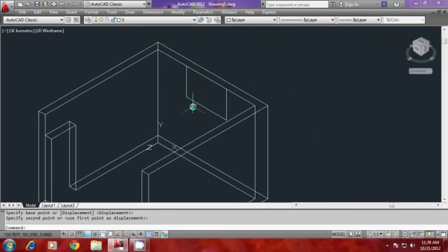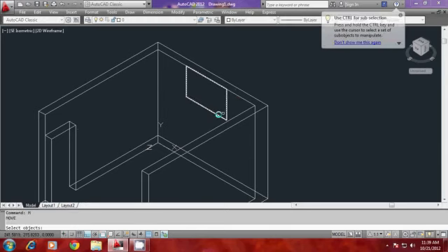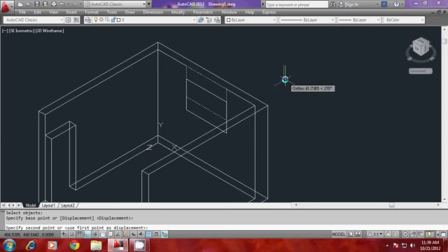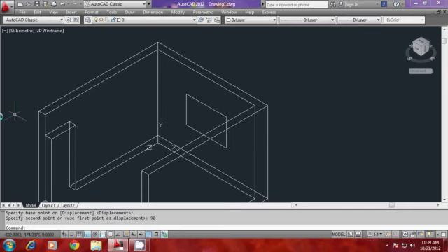centrally with this wall. Now I should move this window all the way down to match with the lintel. So I should bring it down to the lintel level. So I'll go to move command, I'll select the profile of the window. I have selected the base point. It can be anywhere on the screen, and I have to move straight vertically down. So I point my cursor in the Y direction, and I'll give a height of 90 units. So it has matched with the lintel.